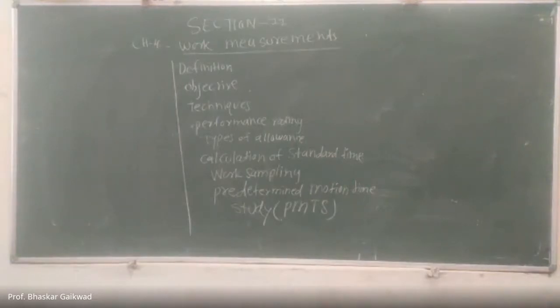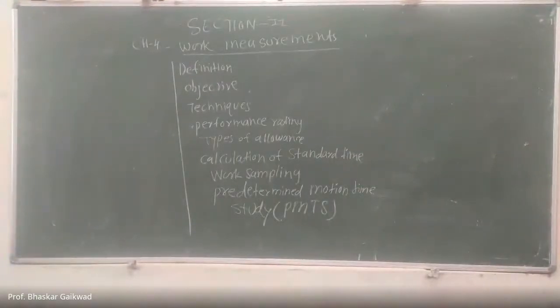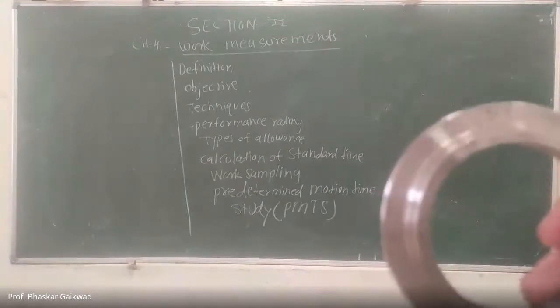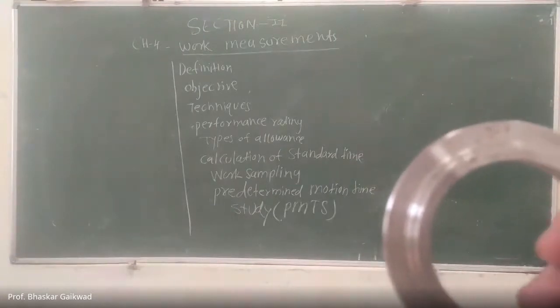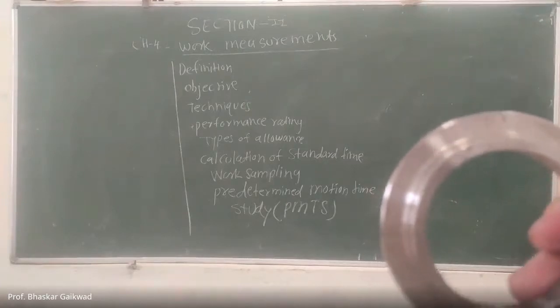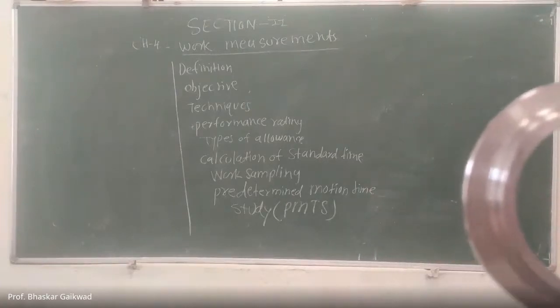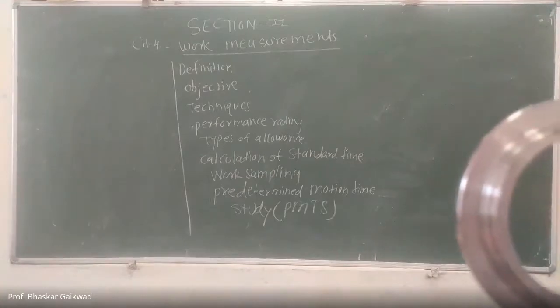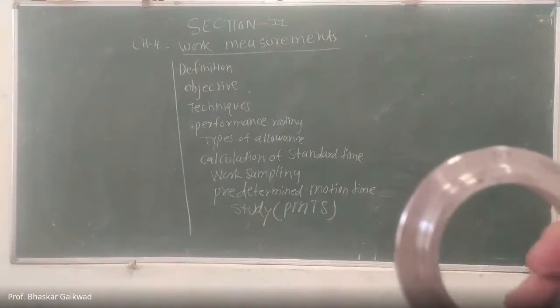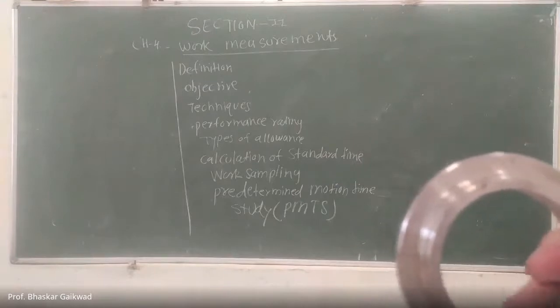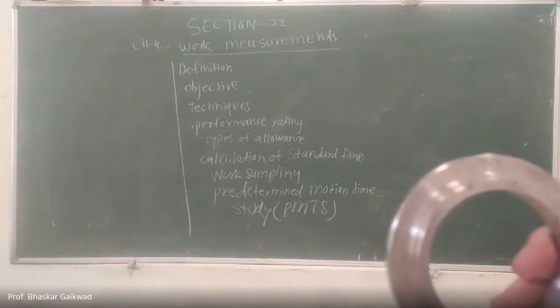So first we have to calculate the basic times or normal times required to manufacture them. So how do we calculate? First, the observed times, observation actually we have to make on those machines. On that machine the person is working, we suppose there is 100% performance, a highly skilled person, a standard person.